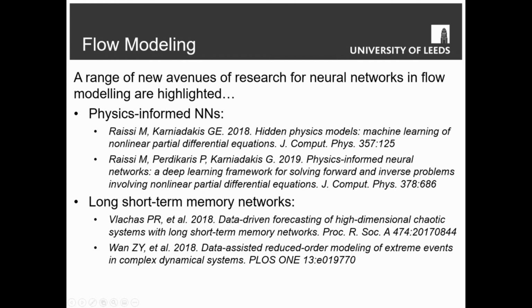The paper also talks about another interesting and challenging problem around long short-term memory networks. I'm really short of time and I'd love to talk about this in more detail, but basically I've talked so far only about steady state problems, but of course most flow problems of interest are time-dependent, and so really what we're trying to produce is an entire time sequence of outputs. What we could do in a naive way is say, if I know what the flow regime is at time tn, can I use a neural network to produce an estimate of what the flow field will be at time tn plus 1?